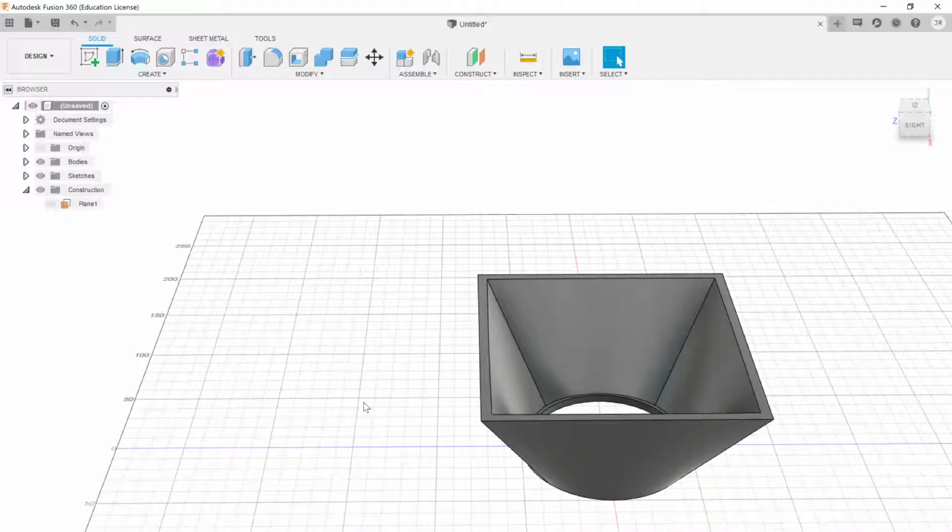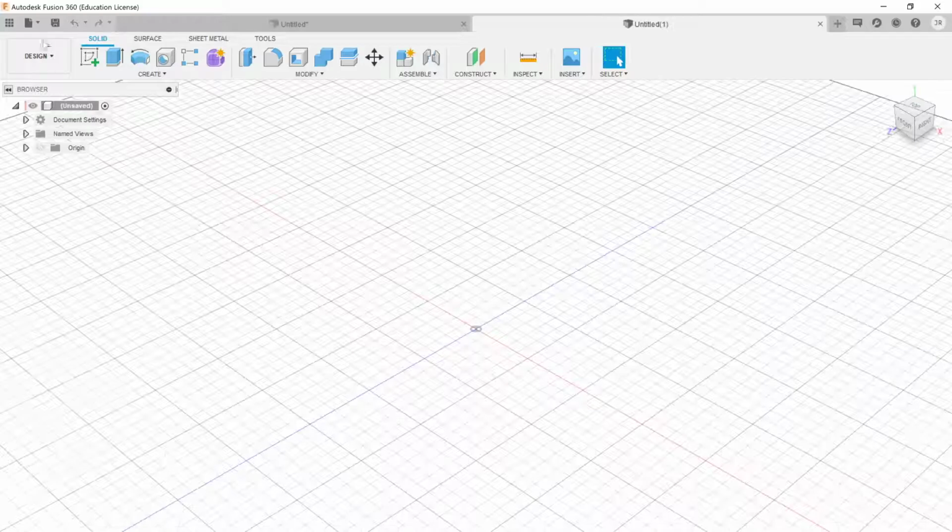So the next tool we're going to use is the Sweep tool, which is very similar, but the big difference is that instead of going from one drawing to another, we're going to drag a sketch along a line, a path, in 3D or potentially in 3D, and the result is a 3D object. And this is a pretty powerful thing. So I'm going to make a new design just so we have one. I'm not going to mess with this one anymore. There we are.